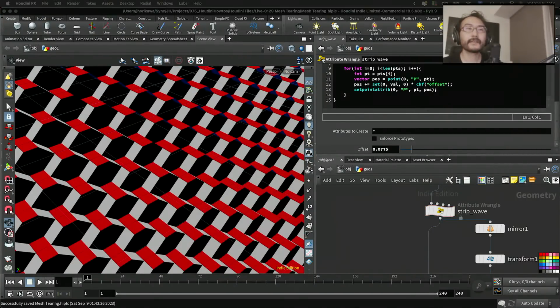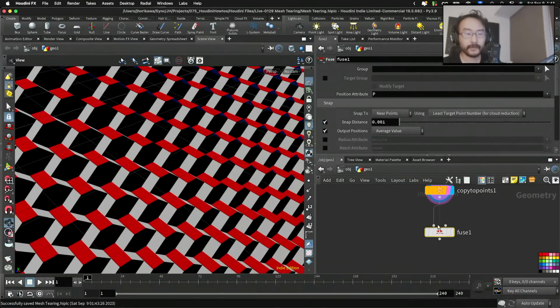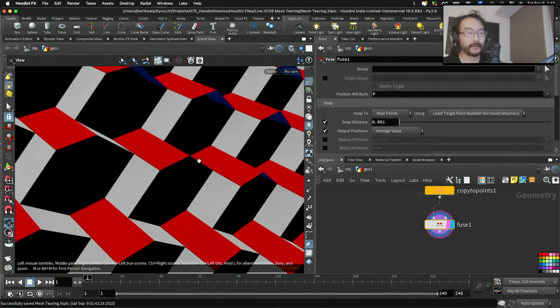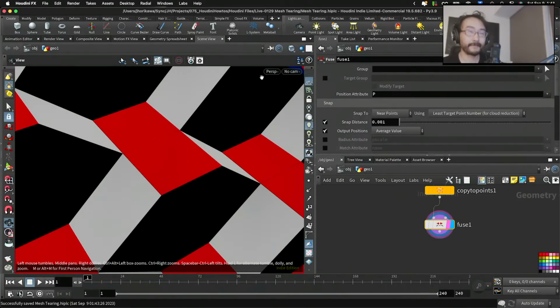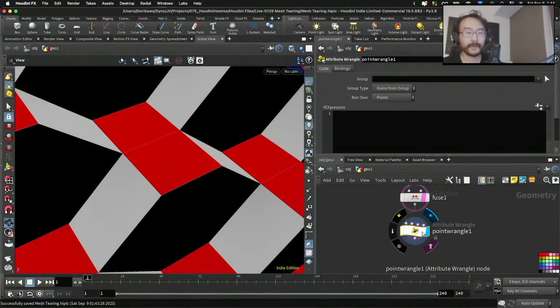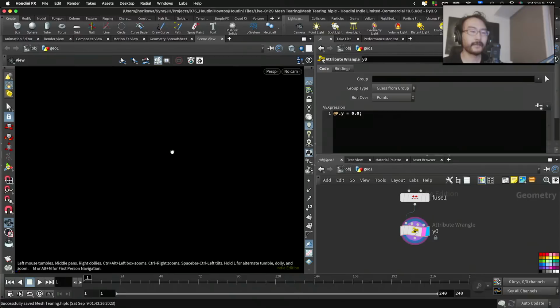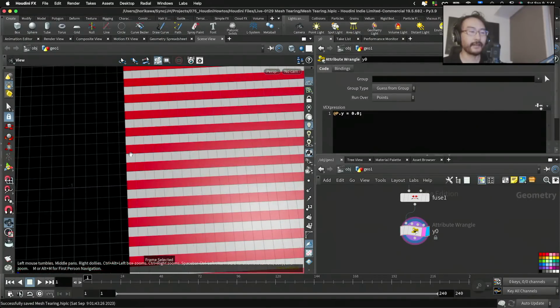Okay, save this, and it's time I set up Vellum shape. Okay, so first I am going to make it fused at this point so that I can only connect the points which are touching right now, right? Then at this point I can reset the height to 0 so that it will become flat, meaning I'm just going to update the y value to 0, which gonna make it flat, but actually it has an opening.